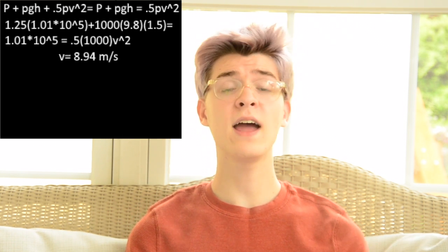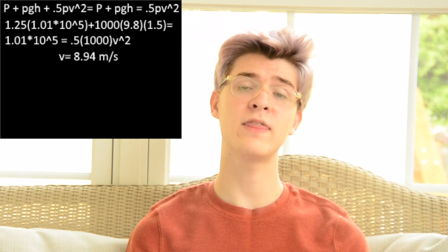Then we can set that equal to our 1/2 rho v squared plus our 1 atmospheric pressure. We do not include the rho g h term in this because the water is now at our reference line, and thus it has no height. We include our 1 atmosphere of pressure converted into pascals because the water at the other side of the hole is going to be exposed to air. Then we plug in our 1,000 kilograms per meter cubed for our rho, and we solve the equation for V. Once we evaluate this equation, we find that V is about 9 meters per second.